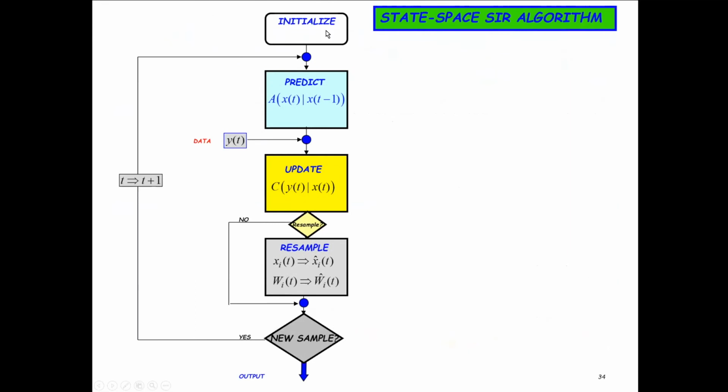It looks like this. Even in a Kalman filter structure, you go through a prediction step. This is the particle filter using the state space model. The data comes in, you go through the update step, and then there's this other little tiny box that creates a problem. It's called resampling, which I'm going to talk about in a minute. You have to resample the particles, recalculate the weights, and now go back up and do the next sample.